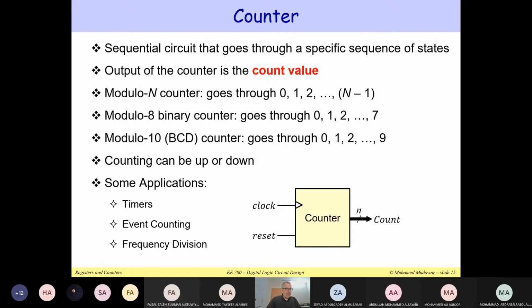We have seen, for example, how we can implement a sequential adder and how we can add the bits sequentially, starting at the least significant bit. We can save the carry out and use it as a carry in for adding the next bits. Then I can save the sum bits in a shift register. After repeating n times for all the n bits, we can output all of these n bits in parallel at the output of the shift register. So we can shift and save the sum, and output the final sum. So this is good, we can design a sequential adder in this way.